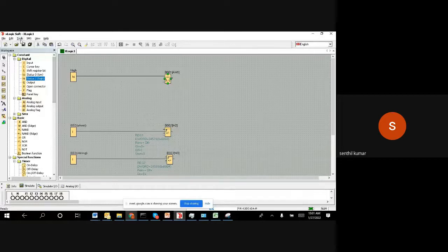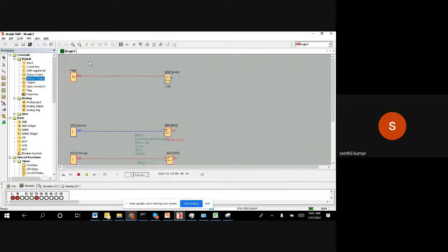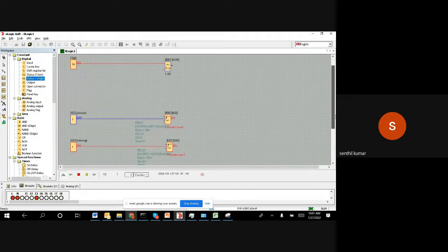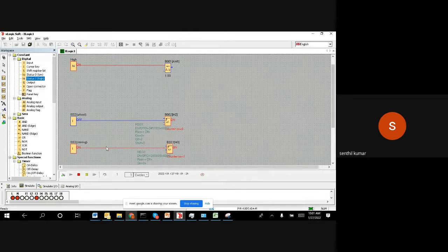Right? So I'm going for this simulation. So now let us see the count. If I look at the count, the I003 is on, and the count is 1. That means one steering got produced already, whereas the wheel count is 0 because there is no production so far. So 1 plus 0 is 1. So you can see the calculation block top. The 1 is the actual result again.